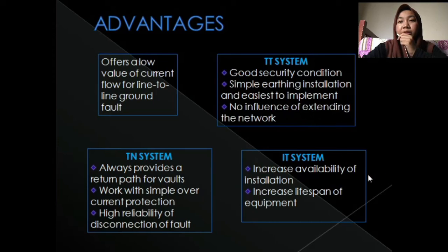And for the IT system, it increases the availability of the installation, because with the IT system the current cannot be looped through the transformer neutral, so the first fault current value remains very low. And the IT system increases the lifespan of equipment due to the very limited fault current in the IT system.